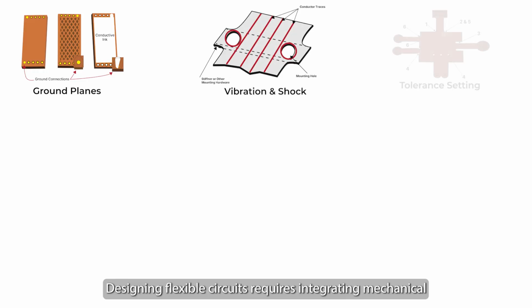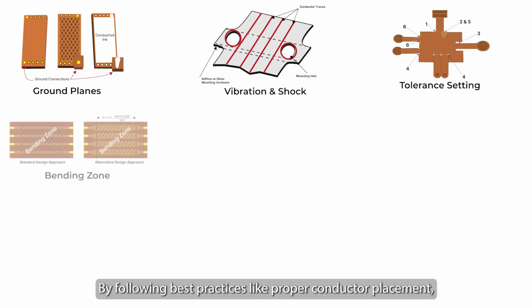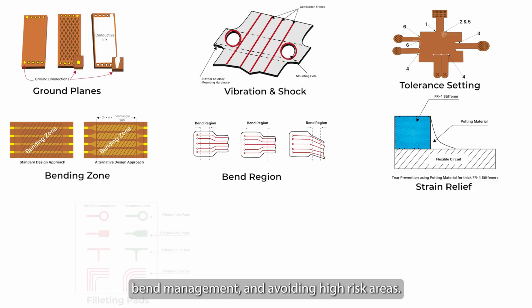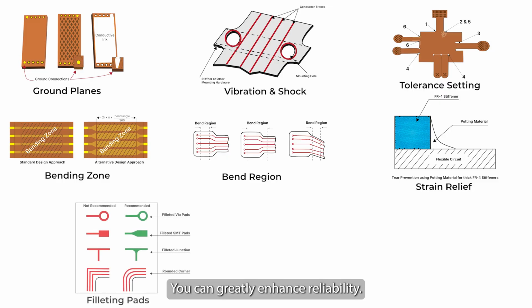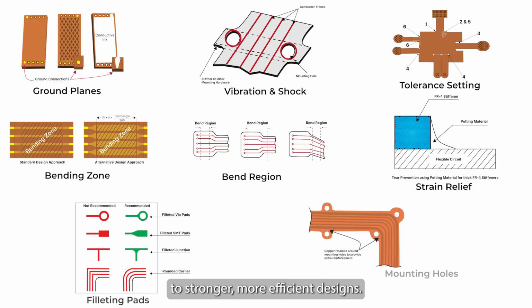Designing flexible circuits requires integrating mechanical and electrical principles to ensure long-term performance. By following best practices, like proper conductor placement, bend management, and avoiding high-risk areas, you can greatly enhance reliability. Adapting these strategies to your application leads to stronger, more efficient designs.